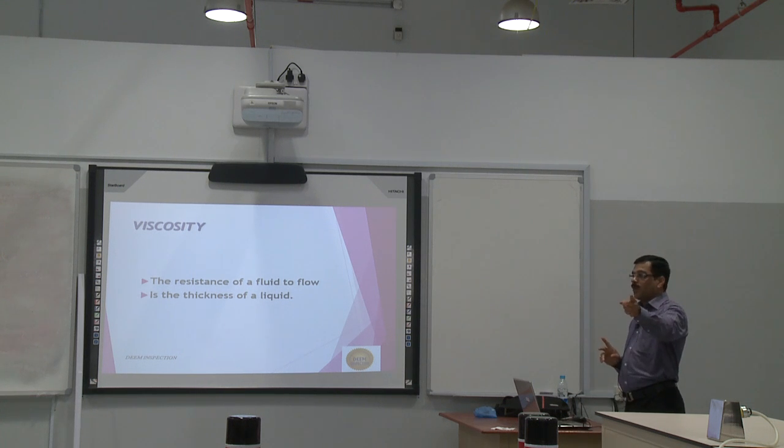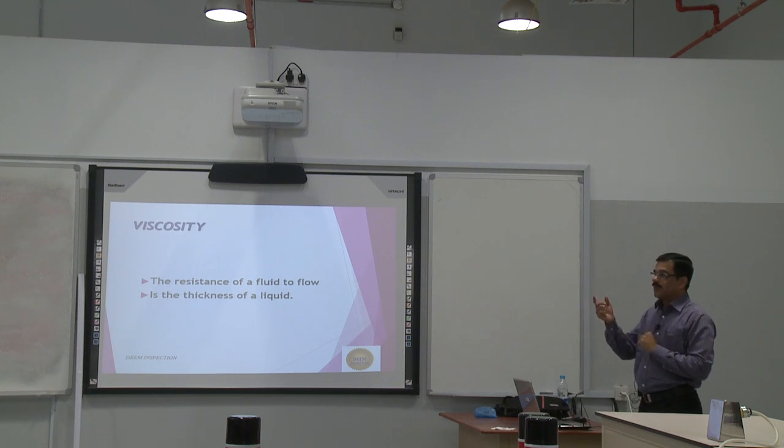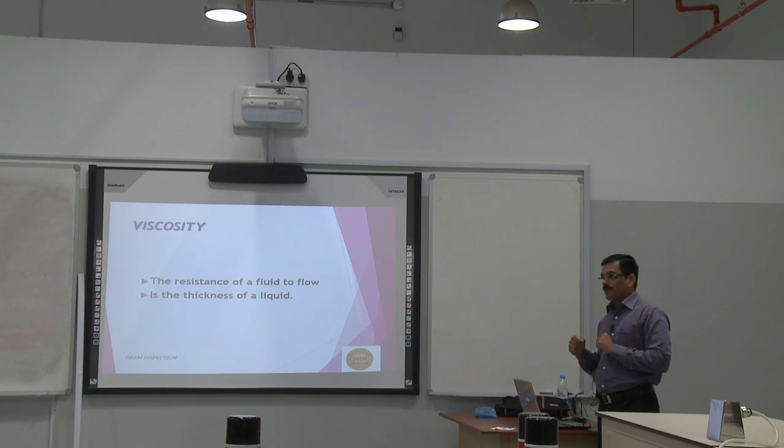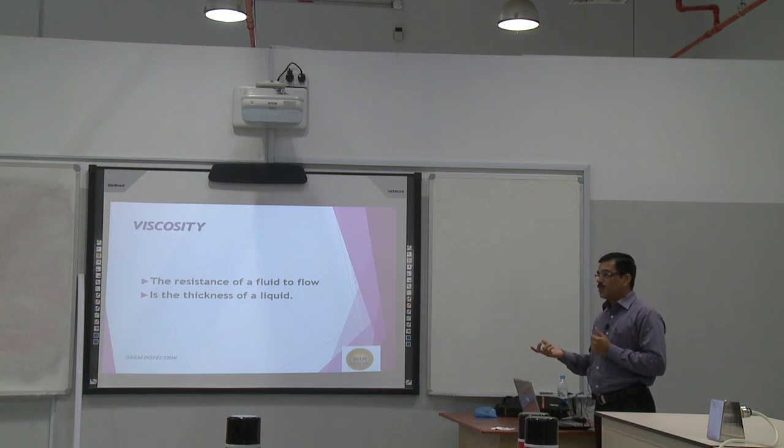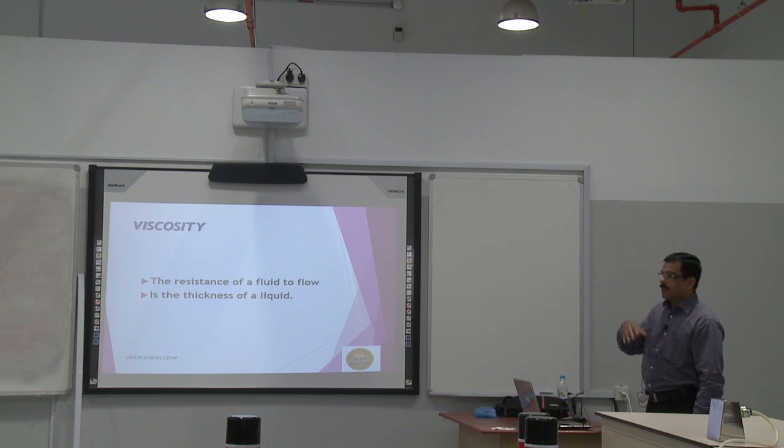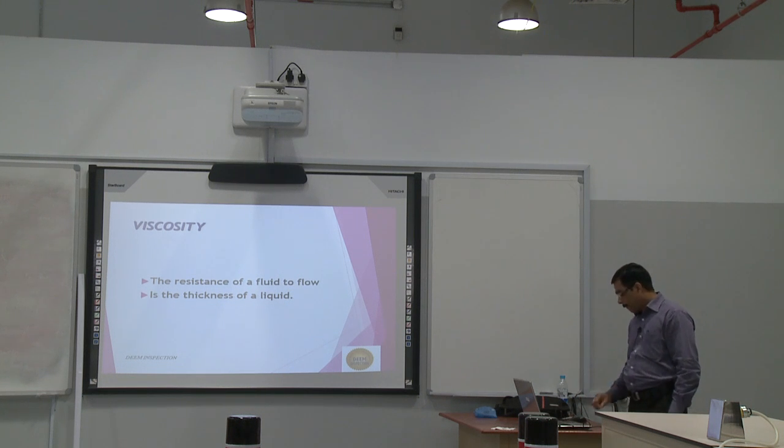Penetrant comes only in this color in the visible type, and otherwise fluorescent, in yellow-green color. Mostly the dye penetrant is red, maybe because industry is everywhere black in color, so red is immediately noticeable. If there is any defect, it's easy to identify. Maybe that's the reason they are using red dye penetrants.